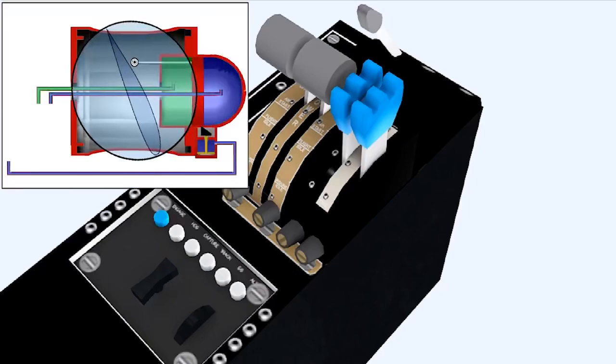As the pitch of the blades coarsens to allow the propeller to absorb the increased torque being produced by the engine, the piston in the pitch change mechanism moves into the flight pitch range, or alpha range. This allows the flight fine pitch stop to engage under spring pressure, thereby preventing the piston from moving below the flight fine pitch position. There is now sufficient RPM available to bring the propeller control unit on speed and into a controlling condition.